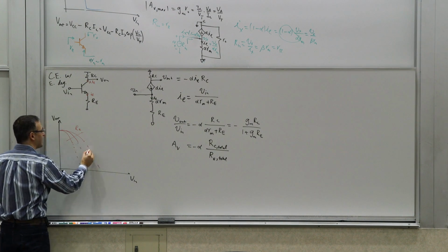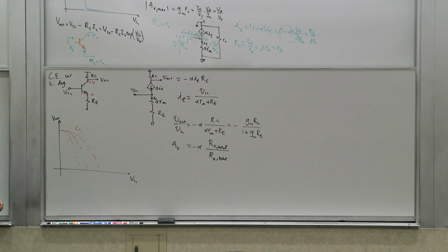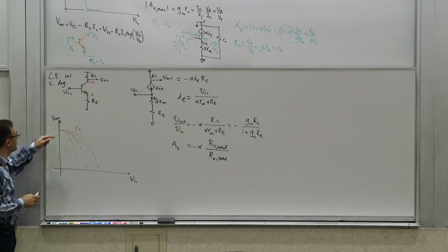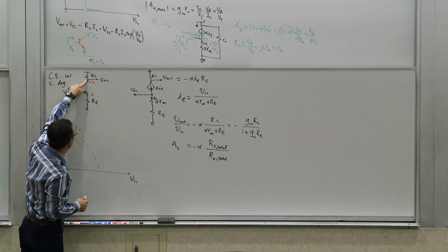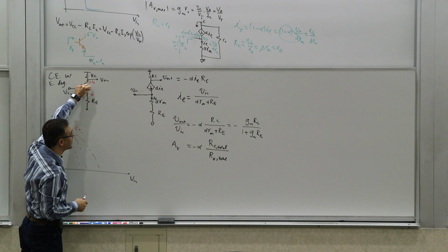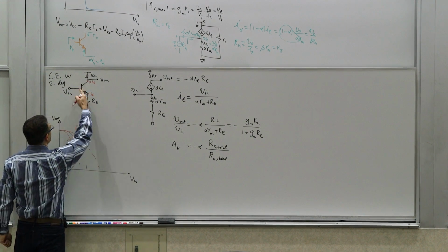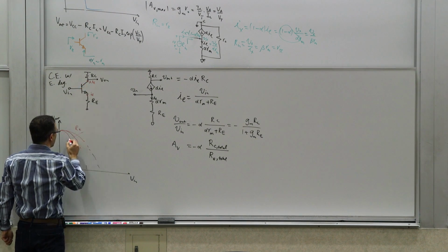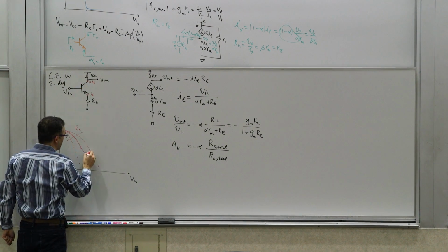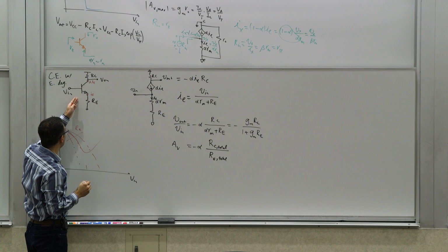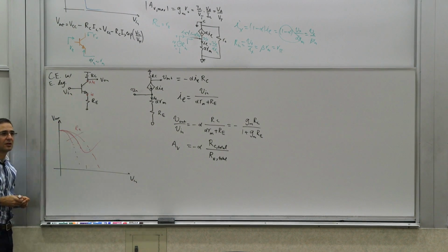And you know the answer already, right? It doesn't, because at some point, this voltage becomes high enough that this junction, basically these two get close to each other. This device goes into saturation, and beyond that, essentially, this guy will track that because this junction is forward biased. So you have something like this, and then it may come back up if you just use it like this and calculate the V in, V out.